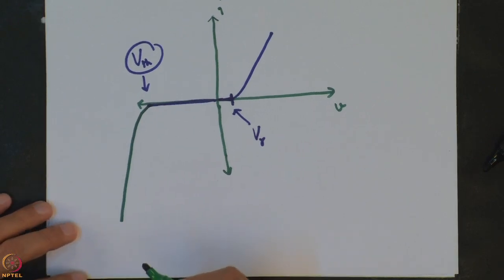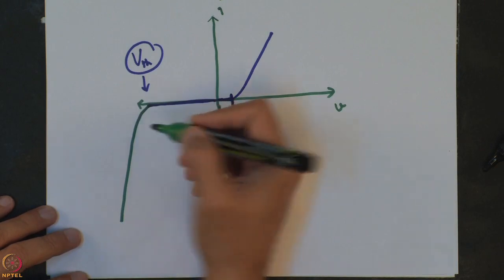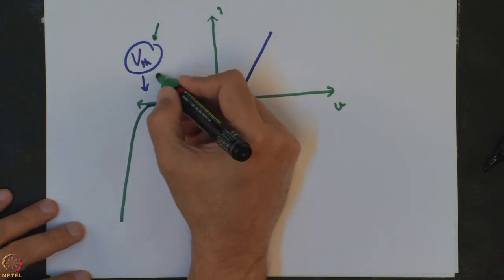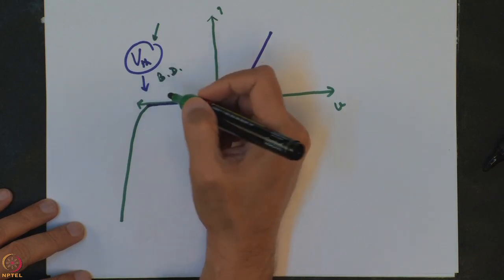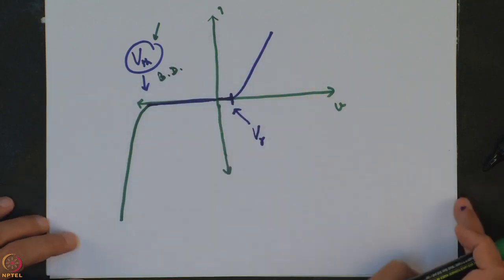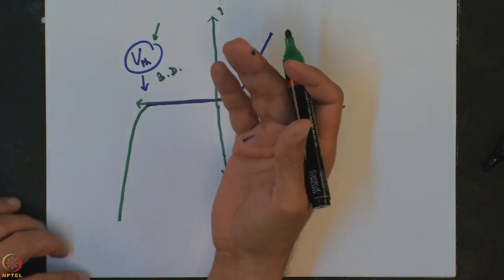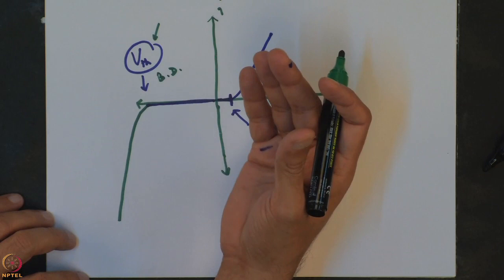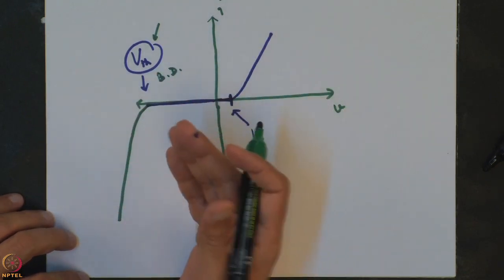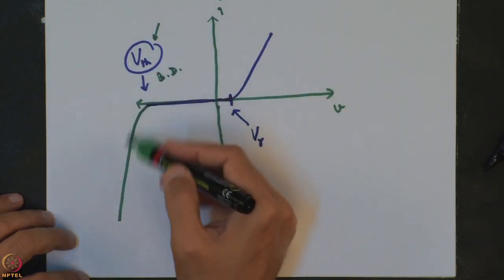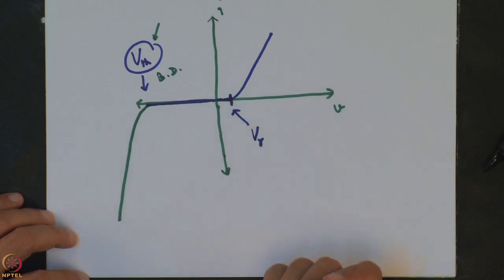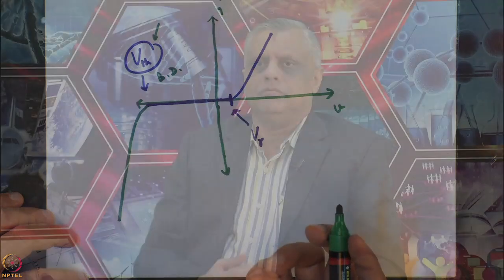Because of this, the threshold voltage is more commonly called the breakdown voltage, because the diode has basically broken down. Now a reverse current has taken over, which is a very high value. A huge current would flow unless it is limited, and it would actually destroy the Pn junction.